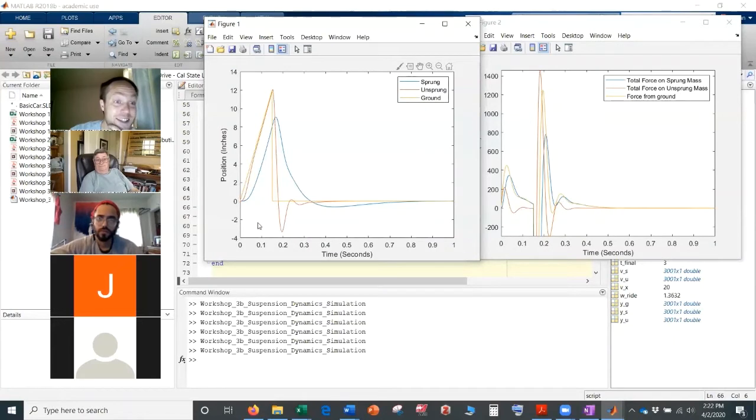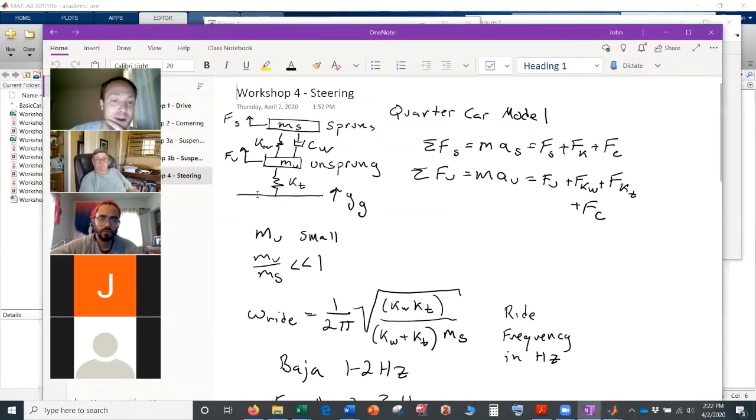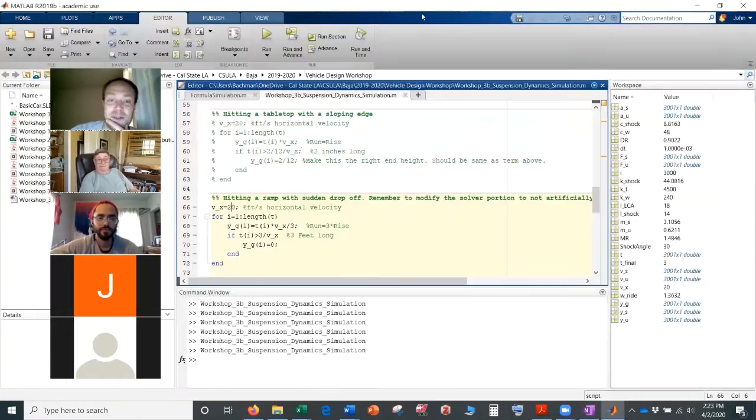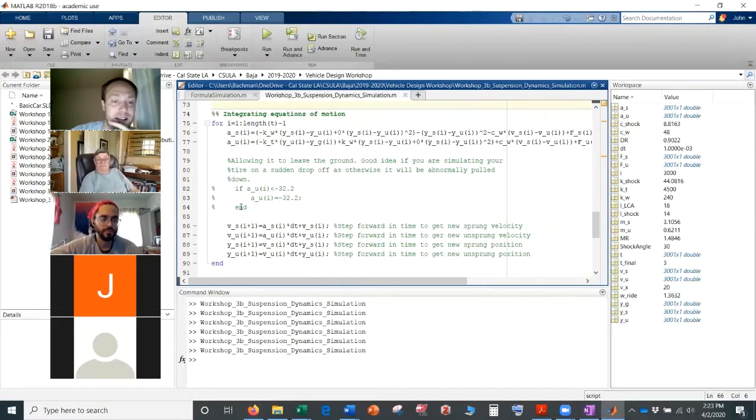And the reason that is you go off a jump, but right now I'm not letting the bottom of my tire leave the ground in my model, right? This spring basically is hooked to the ground. So we need to do a little fix. So what we can do, for example, is I gave it this little part right here yesterday, where we said it can't accelerate more than -g downwards. We're going to limit the acceleration down basically. So that's how we're going to fix that little problem.